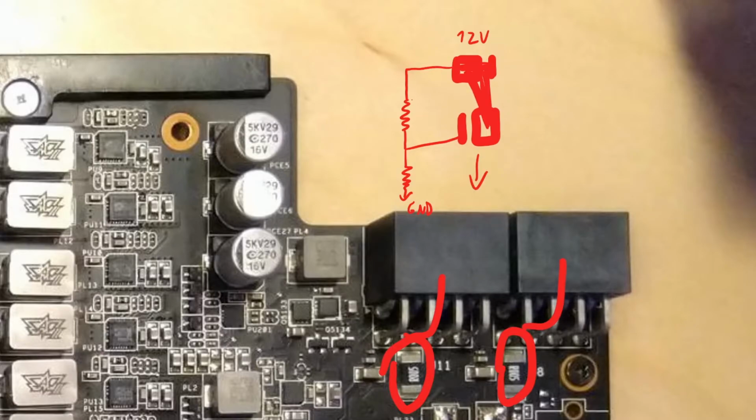The 2 big pads are for power transfer, so that's where the power goes through. The small pads are the ones that are connected to the INA3221. So there's one on the 12 volt side and there's one on the output side. And those pads are used to measure the voltage difference.